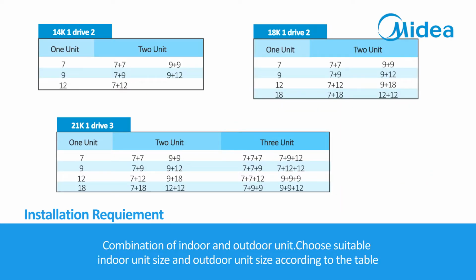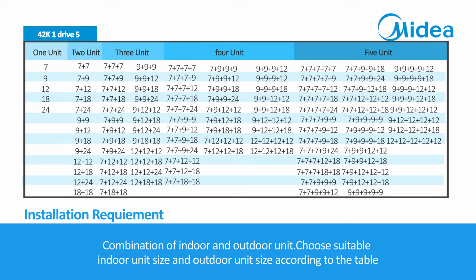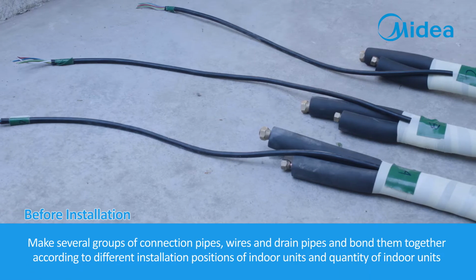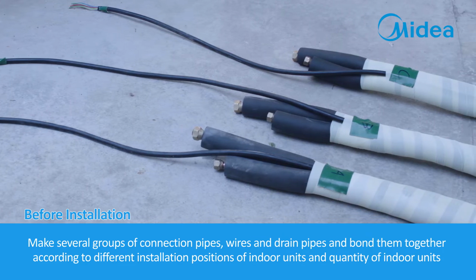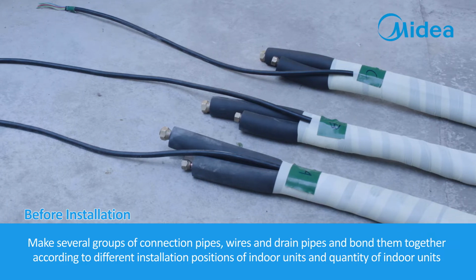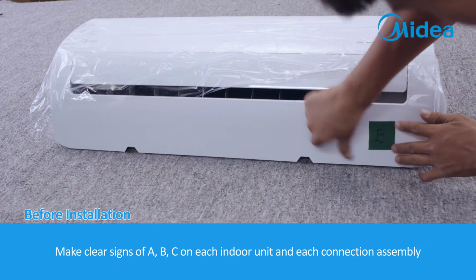Combination of indoor and outdoor unit. Choose suitable indoor unit size and outdoor unit size according to the table. Before installation, make several groups of connection pipes, wires and drain pipes and bond them together according to different installation positions of indoor units and quantity of indoor units. Make clear signs of A, B, C on each indoor unit and each connection assembly.